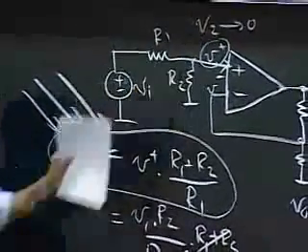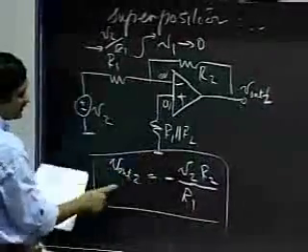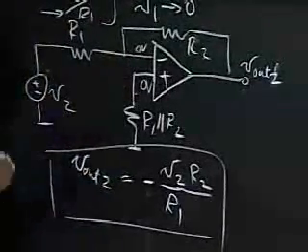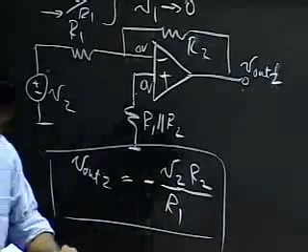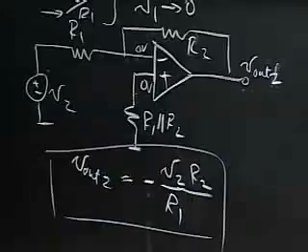Okay, you can pick up another 3 or 4 minutes by remembering this pattern here. This pattern is simply V2 R2 divided by R1. Okay? Imprint those 2 patterns into your brains. Okay. So those are a couple simple circuits using the op amp.